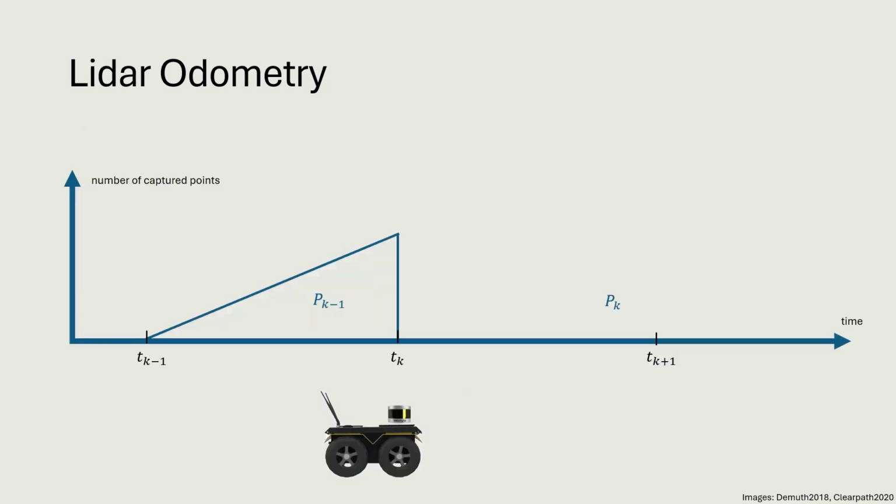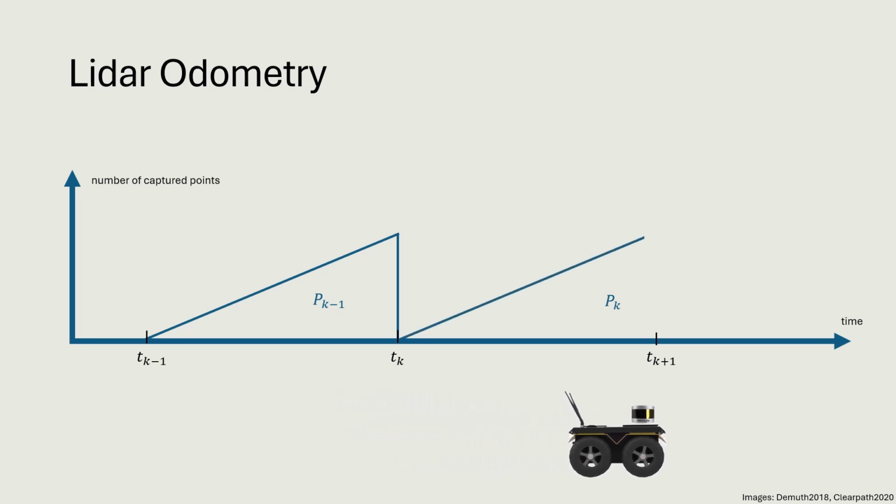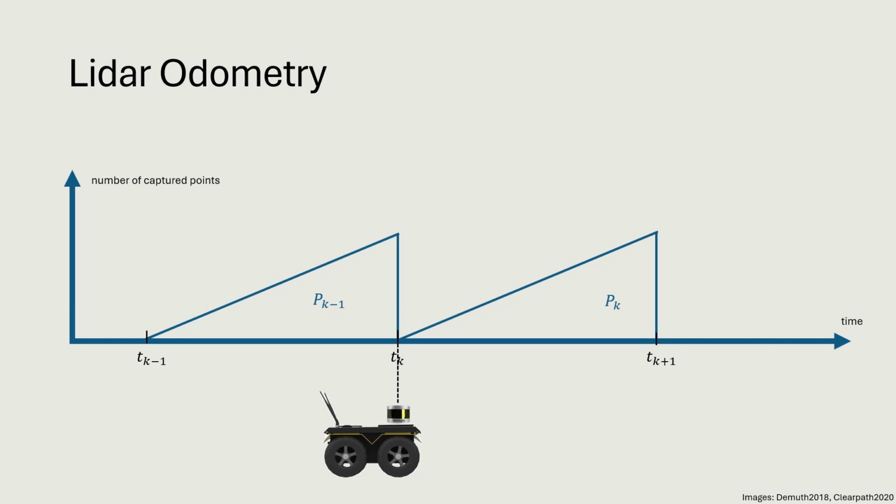The robot moves while the current sweep is recorded. To obtain a realistic image of the environment despite this movement, the recorded point cloud P_k, i.e. the extracted features F_e^k and F_p^k, have to be projected to a fixed pose. In LeGO-LOAM, the pose the LiDAR holds at the beginning of the current sweep k, so at the time t_k, is set as this reference point. Simultaneously, the feature sets F_e and F_p of the previous sweep k-1 are projected to the same point in time, so that we are able to find correspondences that make sense. Now, for all the features from the sweeps k-1 and k, it can be assumed that they were recorded from the same position and orientation and at exactly the same point in time.